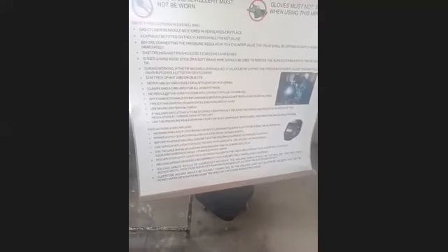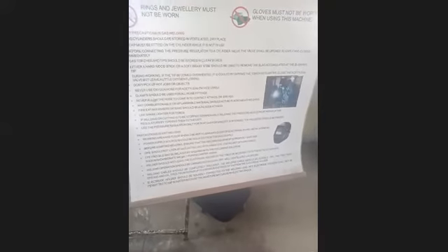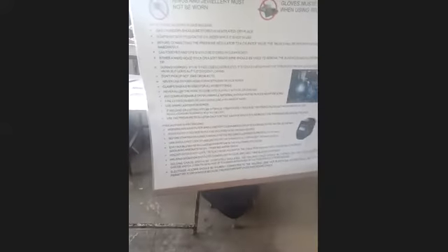The next precaution is that eye trouble may be relieved by washing with the following solution: sodium bicarbonate, then purified water, etc. Welder should not leave the electrode holder on the table or in contact with the metallic surface. Welding operation should be carried out in clean, dry, well ventilated locations. Welding cables should be completely insulated.